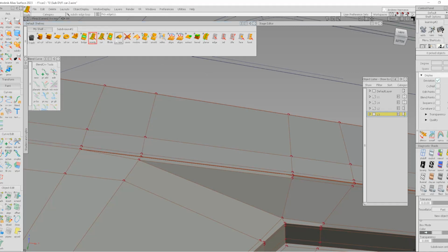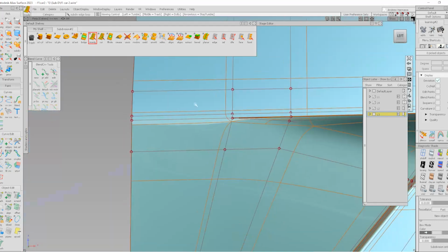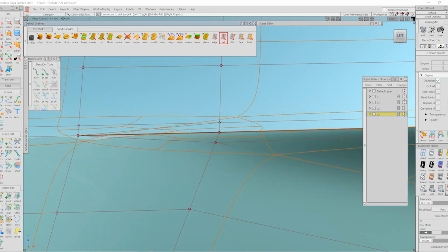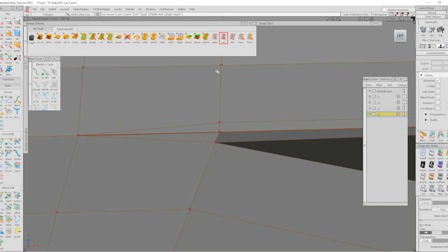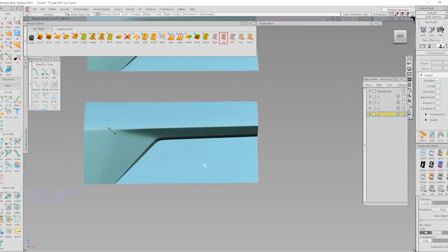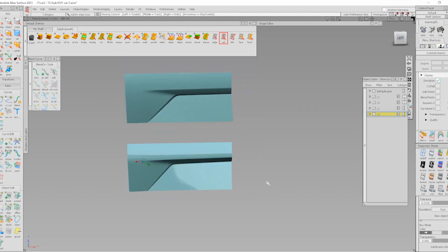Go here, and I don't want it to go all the way because it's supposed to wash out. So I'm gonna use the cut tool. I'm just gonna cut it from here to here, and then get rid of that. And I can also, since I have two three-sided surfaces, I can get rid of this one. Now I have one four-sided surface, and then that goes to a point, and then I can select all of that and then uncrease it, and that will create that washout effect, just like that. Alright, so there we go.